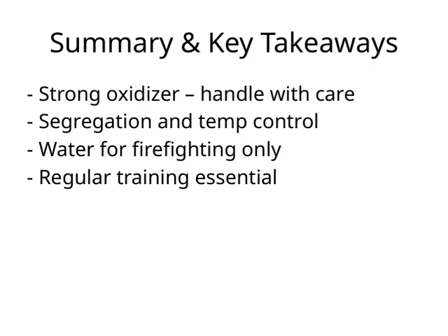Let's wrap up with some key safety points. First, remember that this substance is a strong oxidizer, so handle it with care at all times. Next, it's crucial to keep it segregated from incompatible materials and maintain proper temperature controls to prevent any reactions. Water should only be used for firefighting purposes, never to try to extinguish a spill or fire involving this material unless specifically advised.